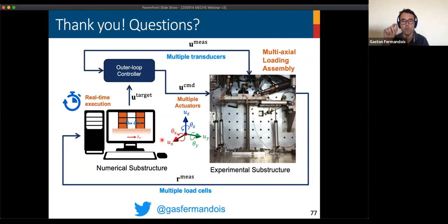So if you change the initial guess for your parameters and run the optimization, you can get stuck in local minima. And you change the initial guess or the initial point again, and you get another result and another result. So this is quite difficult to achieve, especially in Cartesian coordinates. In actuator coordinates, it's not a big deal because the order is small. We are curve fitting the data to a system that has 4 poles, no zeros. So for each actuator it is very simple, but in Cartesian coordinates it's quite hard to do.